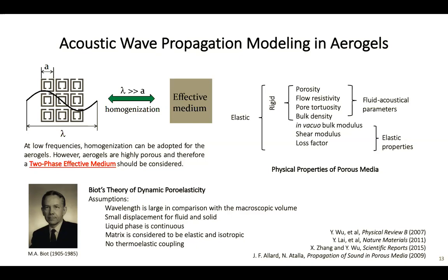We need to have an open cell structure, as we have in the case of aerogels. For example, this theory cannot be used directly for foams, which are mainly closed cell structures. The other thing is we should not have thermal coupling, basically thermoelastic coupling, in the problem. Therefore, with these conditions, we adopted Biot theory.